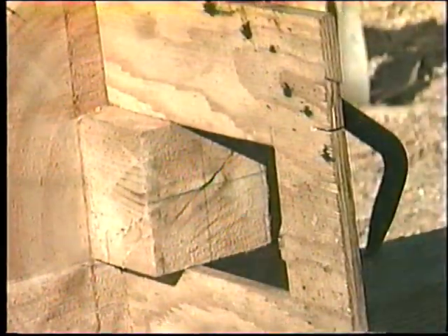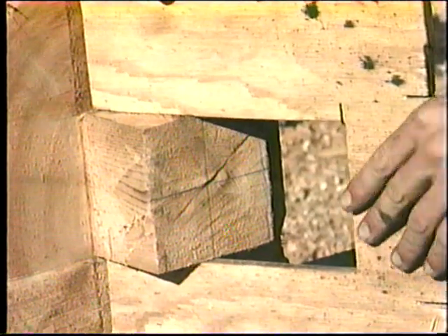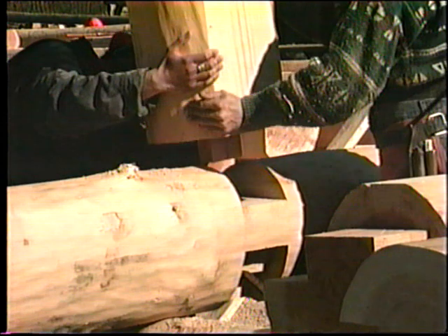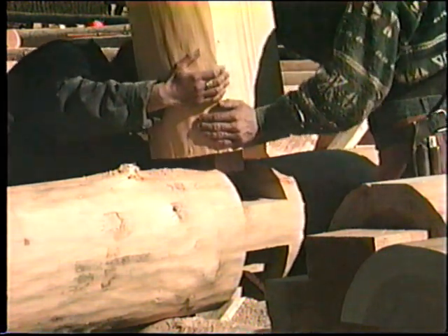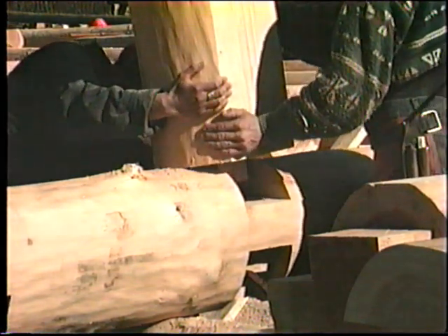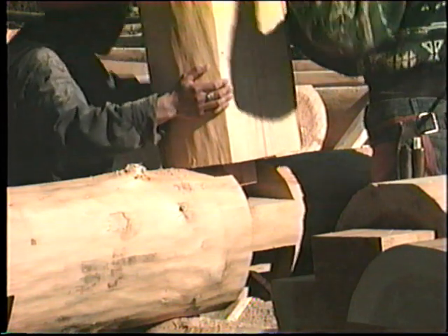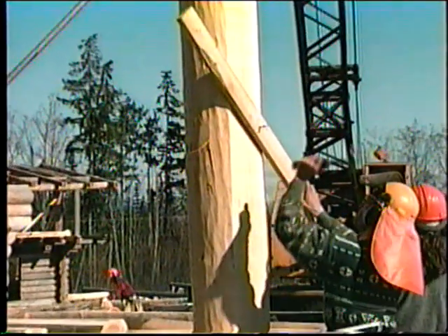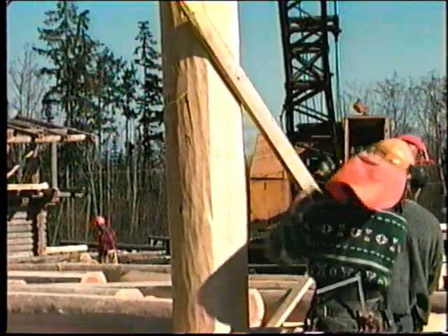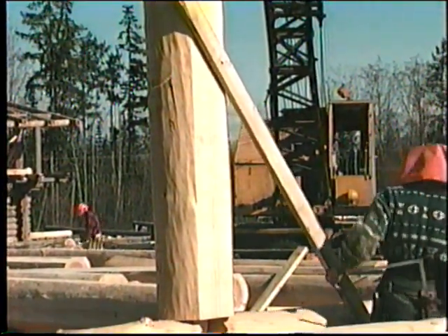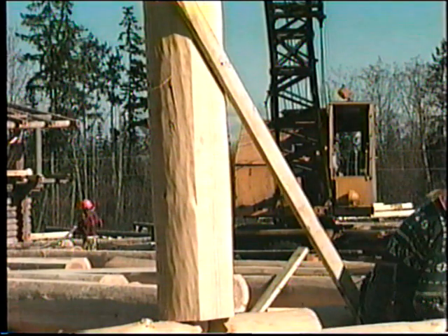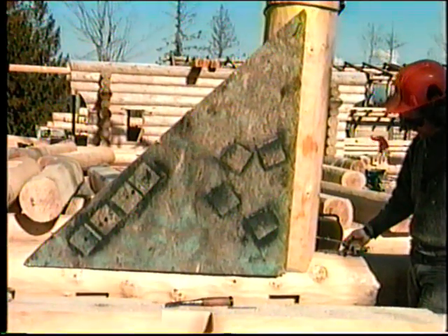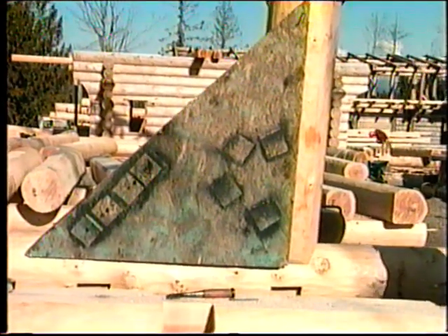When the tenon has been cut and checked with the template, lift the post into a vertical position and enter the tenon into the mortise. Secure the post in a vertical position that is 90 degrees to the reference line. You can use a level to check the end center lines and a 3-4-5 triangle to position the side center line with the reference line. You may also use a plywood right angle triangle to hold the post in place.